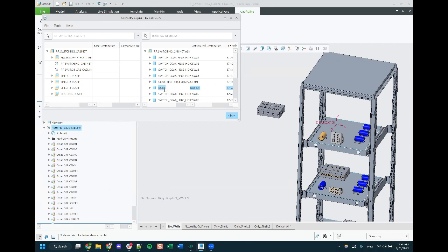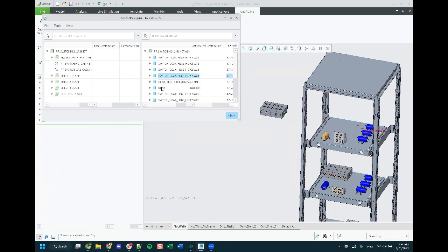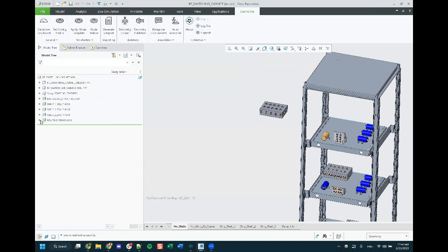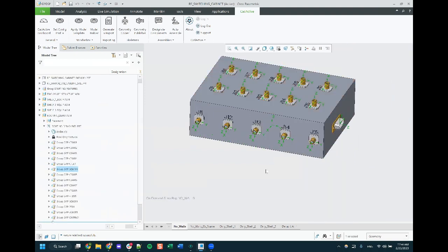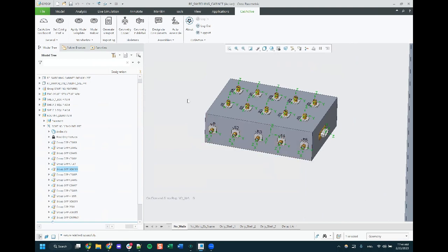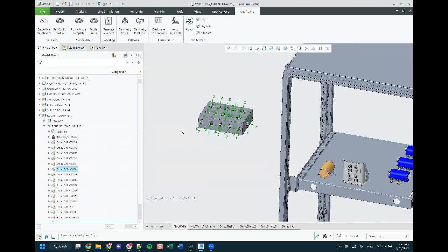But anyways, if I right click on this box 1, we have an option to update location. Now that I do that, if I click back on box 1, we can see, because of some pretty cool stuff that we're doing behind the scenes, we're able to recalculate the position that that coordinate system should be in, even though it has no reference to this box whatsoever. And now, if I go back to my skeleton, all of my external copy geometries have snapped into place. So there's that level of associativity that we have.